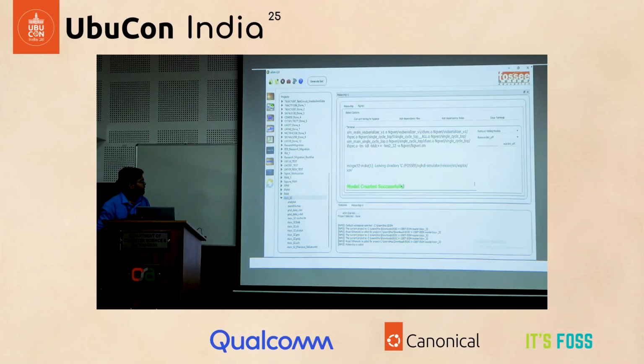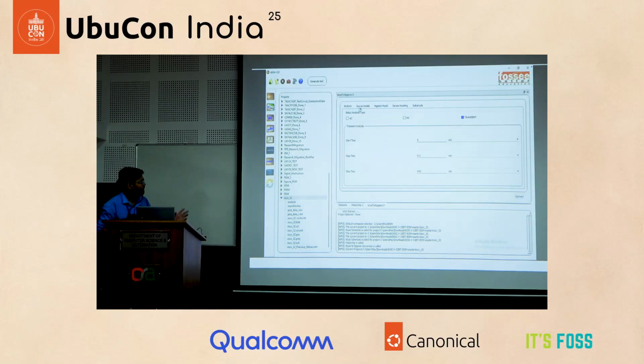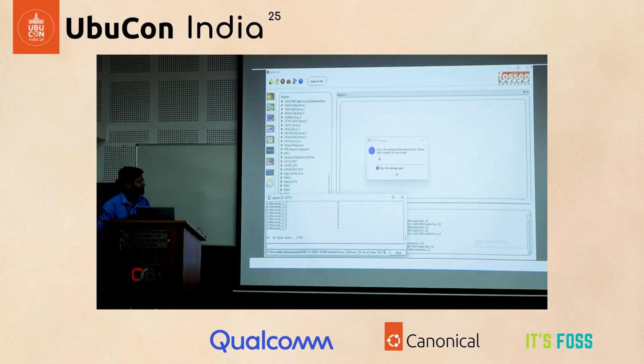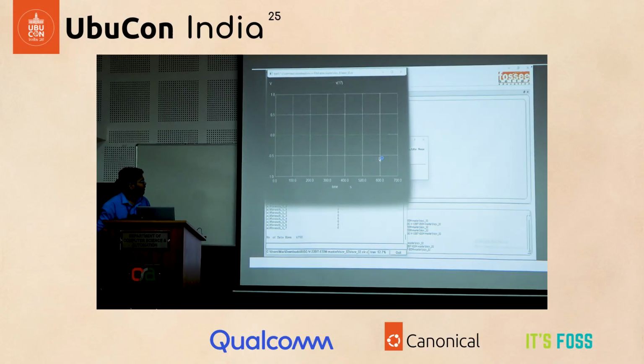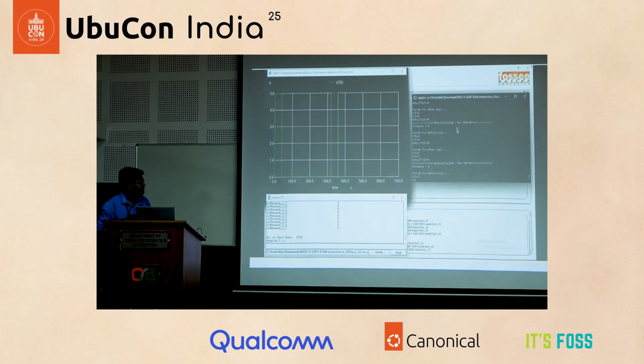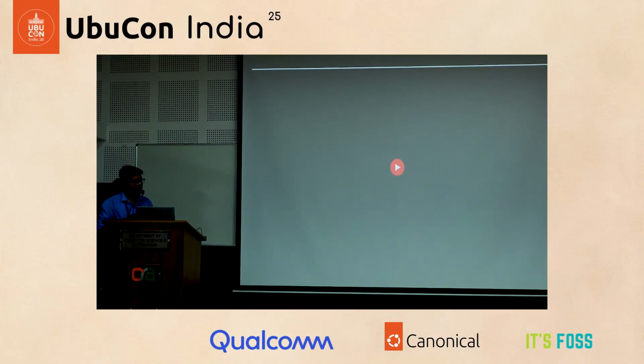Once you've created the netlist, you could go to KiCad to Ngspice, the device console that we saw before, to add all the parameters. So I got another application, it's changed. This is just for reference, to get an idea of how the GUI of eSim looks. These are all the Spice windows that are just popping out. If you want some plotting, it's already there on the main eSim window. And on the other side, you can see the command line values and all. So this is one way to create your IC subcircuit based on Verilog.